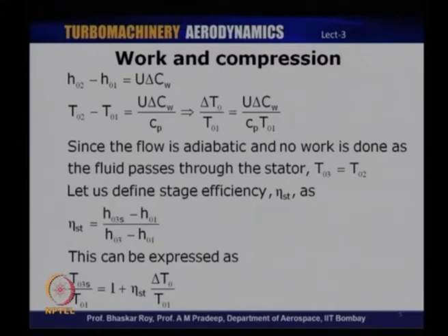So, what we will do now is define what is known as the stage efficiency. If you remember, in the last class we had expressed the compression in a stage in terms of a temperature and entropy diagram, and I had specifically mentioned that deviation of the process from isentropic behavior is expressed in terms of what is known as an isentropic efficiency. Now, for a stage, we will express this as the stage efficiency, which is basically the difference between the enthalpy at the exit of the stage for an isentropic process minus the inlet enthalpy, divided by the actual enthalpy at the stage exit minus the inlet enthalpy.